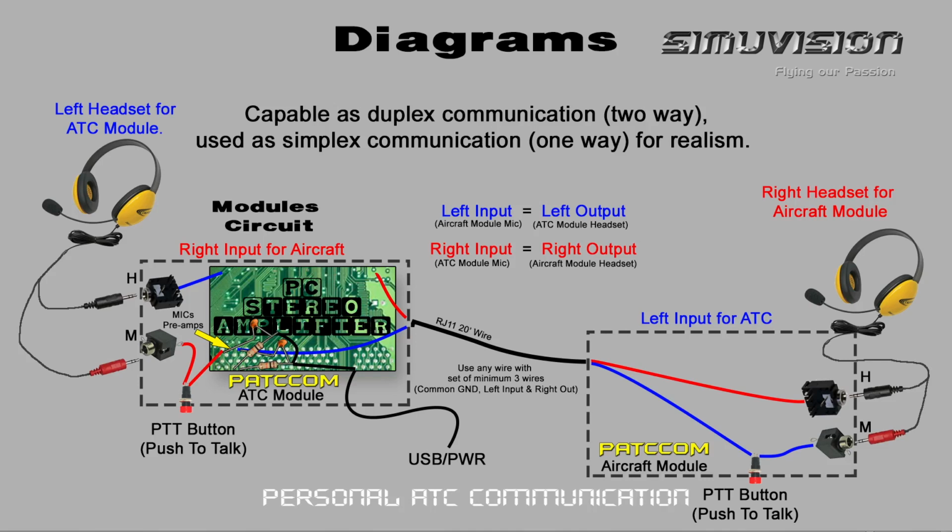Because the microphone does not have enough electric charge to amplify, we need to feed in an external current voltage to the microphone, using resistors and capacitors, which you will see in the next slide. And you can use the same for your preamp as well. So that's what it is. I hope you would be able to make your own.